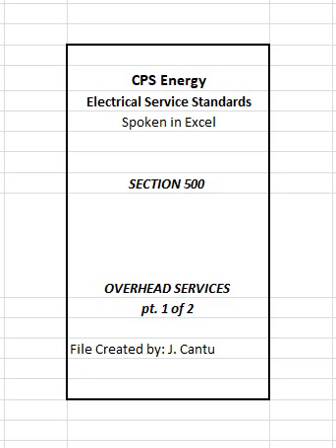502 Vertical clearances. Service drop conductors, including drip loops, shall comply with minimum clearance requirements of the NEC and NESC and with the specific provisions herein for services not exceeding 600 volts nominal, refer to Figure 501. 502.1 Above roofs. Where service drop conductors must be installed above a building or structure's roof, the service drop conductors shall be provided with the minimum vertical clearances shown in Figure 501. The vertical clearance above the roof shall be maintained for a distance of not less than 5 feet in all directions from the edge of the roof.